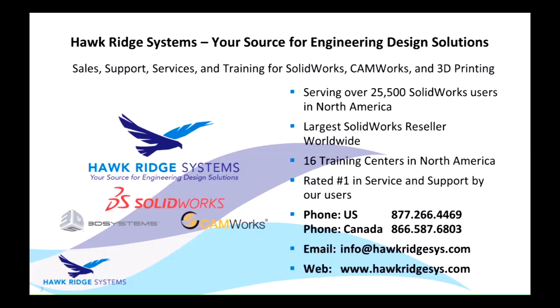And keep in mind that assembly selection mode is key to selecting those sub-assemblies, selecting those sub-assemblies under those sub-assemblies, and rotating them and moving them in context of the top level assembly. So when you move that top level assembly in the animation, those components move with it and are still doing what they're supposed to be doing. And that's kind of the gist of this presentation here.